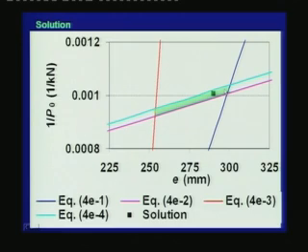If the eccentricity is expected to be a rounded off value, then 290 millimeters is okay, but if there are methods for having precise location of the CGS, then we may increase E beyond 290 within the acceptable zone, and that value will not then be a rounded off number, but it may give a slightly lower value of the prestressing force P0.